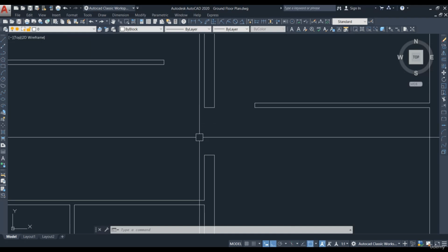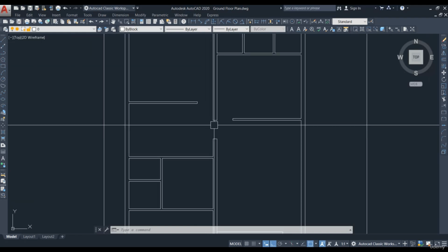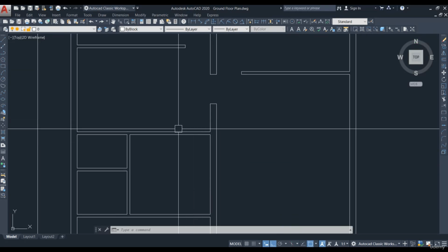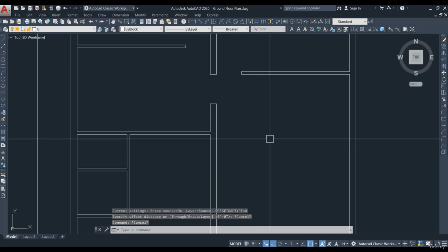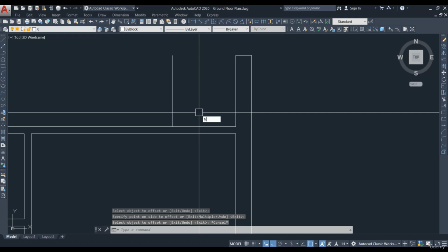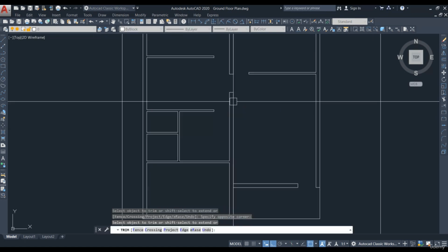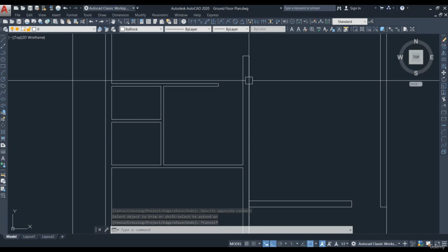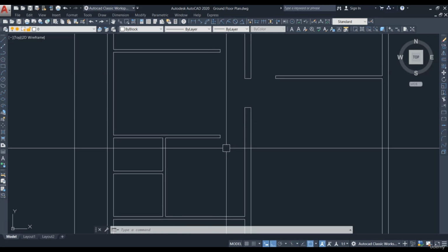Okay, this is an arch kind of opening area. We don't provide a door over here, it's an open free space. And again let's provide the opening for the dining area. Offset 3 feet, trim, shift. So this is also open, no door over here. So that will give you more space, and then you feel like it's a free space.